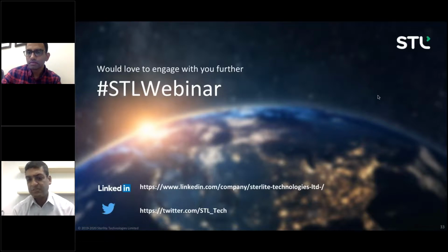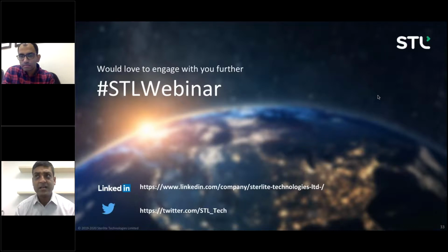splice happens to be right the first time, like with the simplest possible equipment, using unidirectional OTDR, an installer can actually tell that the splice has been done perfectly because the mode field diameter is matched. Yet the fiber that they're using to splice to a legacy network is the best in class when it comes to bend insensitivity. So this is one of the approaches that we have chosen.